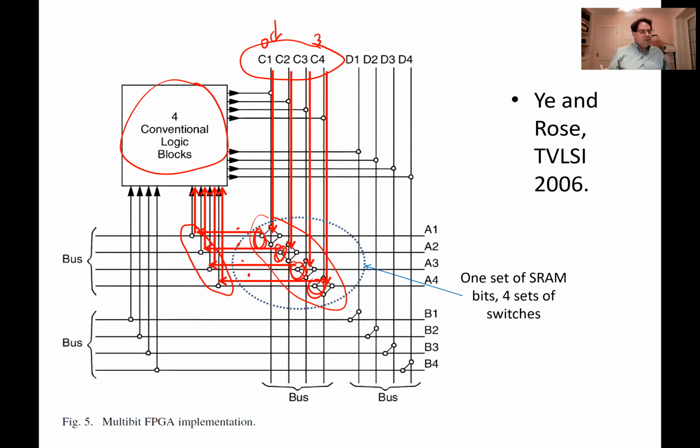So it looks like a conventional FPGA, but some of the routing has been replaced with this bus-based routing, where we have to make decisions on, in what I'm showing you, 4-bit quantities. And those 4-bit quantities will be routed essentially in parallel throughout the island-style FPGA. And then it goes into a logic block that is similarly going to work on 4-bit quantities. Okay, so we're going to take in this data, and it's going to go into 4 separate lookup tables.